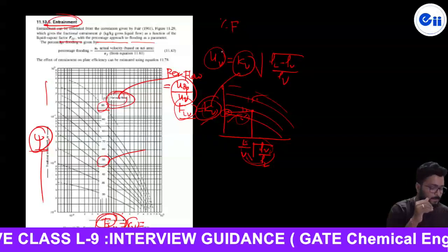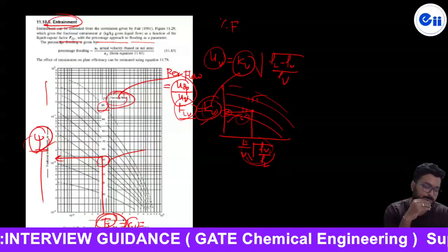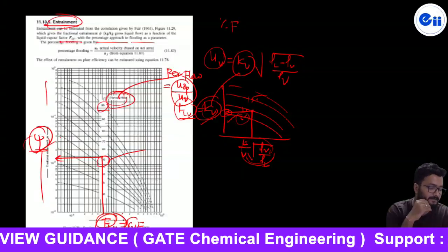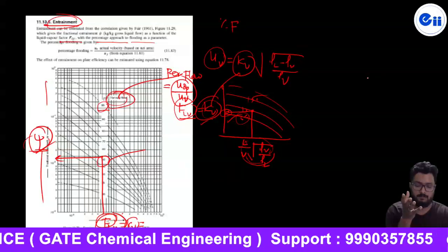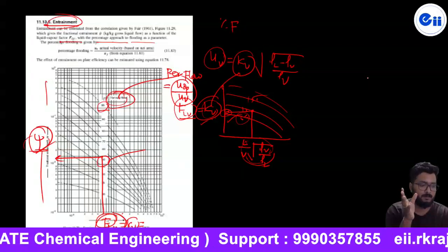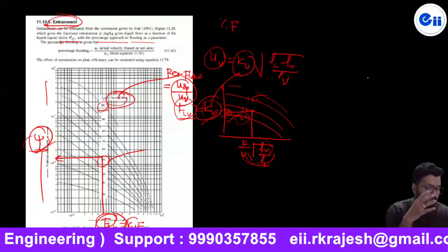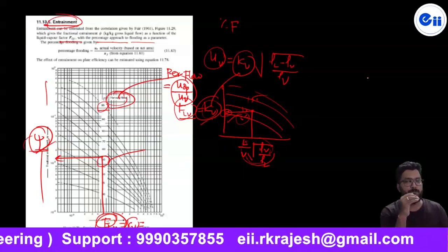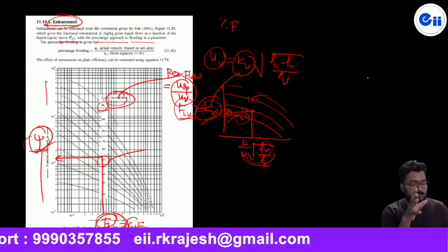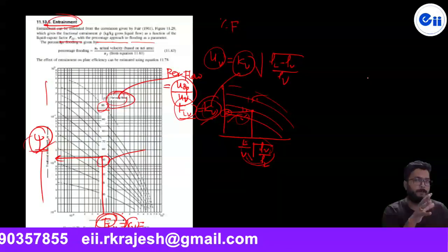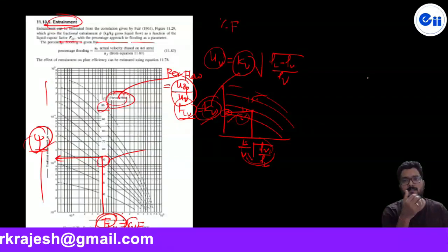So in this way, knowing this and this, we can calculate the fractional entrainment. And the lower the entrainment, the better, so that should be very, very less. So on the basis of this parameter we can check here. It means fractional entrainment is a very important factor, and we can check this by knowing the liquid-vapor factor or vapor-liquid factor called FLV or KV, and also percentage flood.